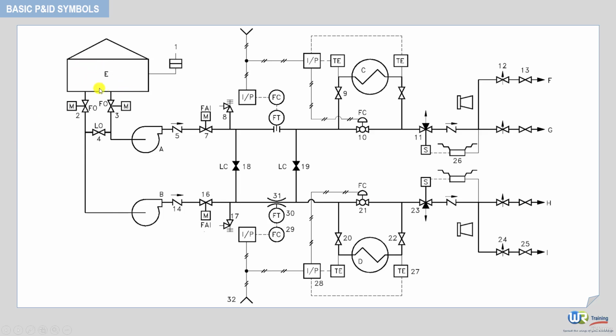So basically here, the tank feeds the pump that you can see here, which conveys the fluid in this direction. On this line, notice also here the presence of two pneumatic to current converters, a bypass line around the control valve with two gate valves, a heat exchanger, and two temperature elements, one at the inlet of the heat exchanger, the other at the outlet. Notice also the presence of a conductivity cell and a radiation detector downstream the solenoid valve.